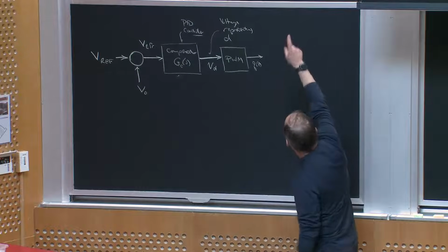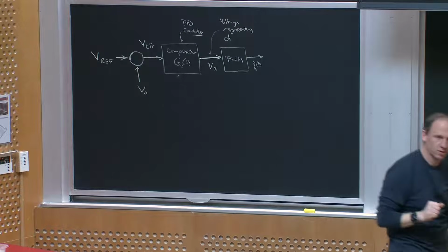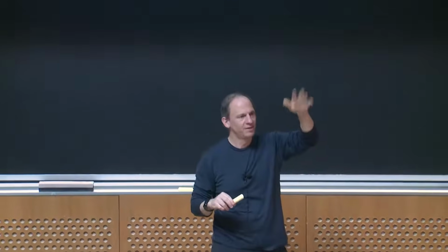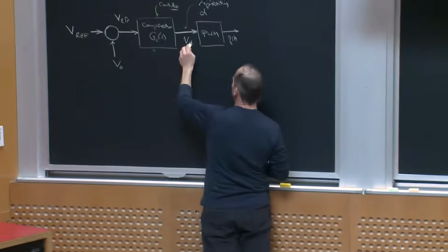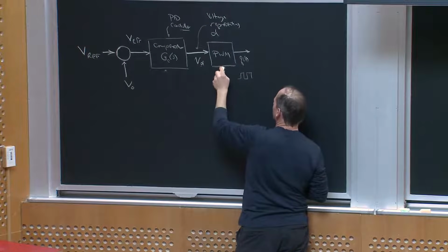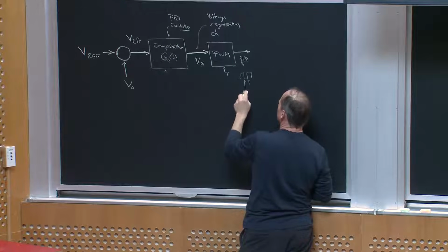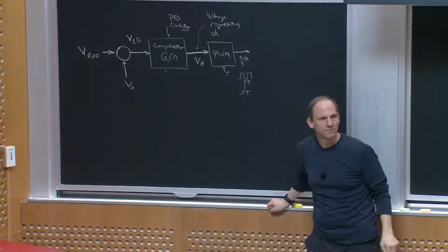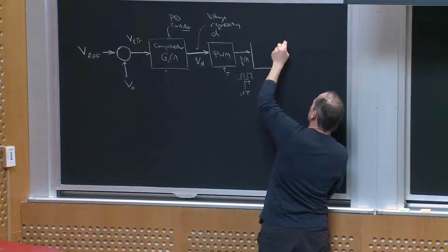Right? Because if I look at up there, I'm talking about in terms of duty ratio, but the actual signal going to my switch is some Q of t or some amplified version of Q of t from a gate drive that's turning the switch on and off at the right duty ratio. So the input of this is some value of duty ratio I want. The output of this is some PWM waveform switching at period t with an on time that's dt. Okay? This then goes into my actual converter.